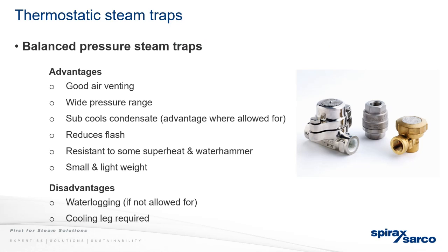The disadvantages: waterlogging, if you're not allowing for it, so if you haven't cleared that properly, and cooling leg required. So that, as we spoke, the length of pipe that's behind it to allow the subcooling of condensate. Do we have any questions on thermostatic steam traps?